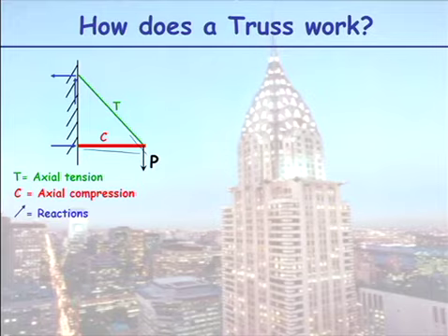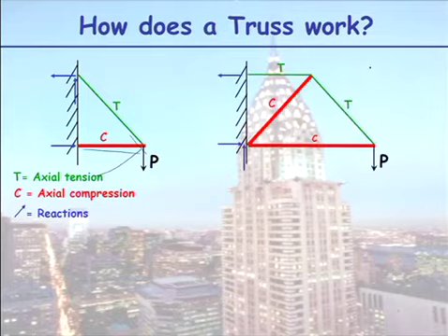And our bottom member here, if that member was just a piece of string or a cable tie, that P force would swing in. So there must be a compression force in the horizontal member. So you can continue working your way out here and ask yourself, this P force pulls down, this member is stretching. If I take this member away, what will happen? This will move inwards, like so. So therefore this member is stopping it moving inwards, so it must be in compression.